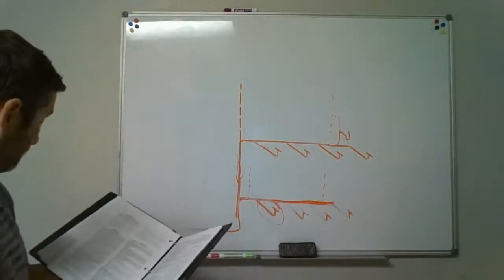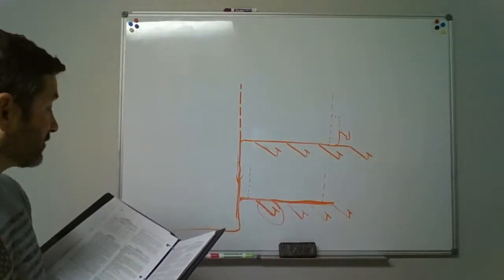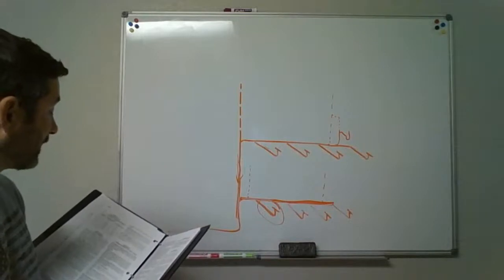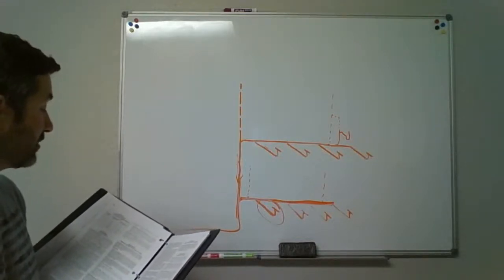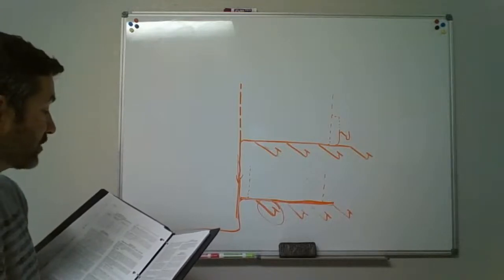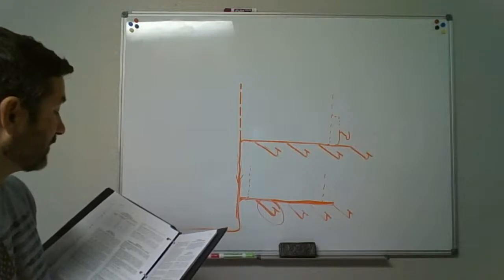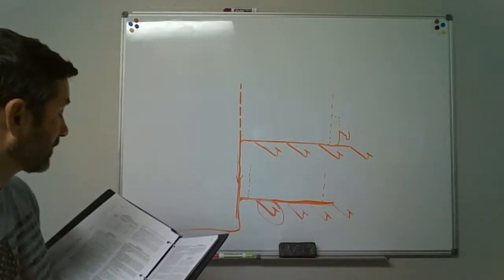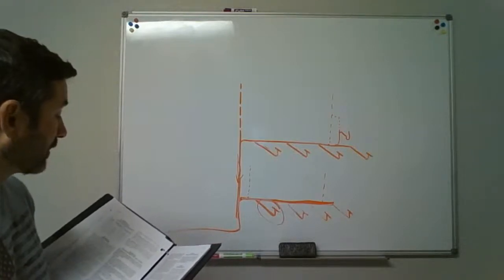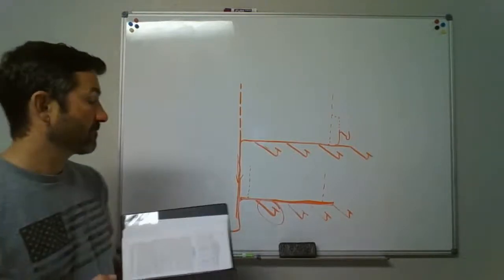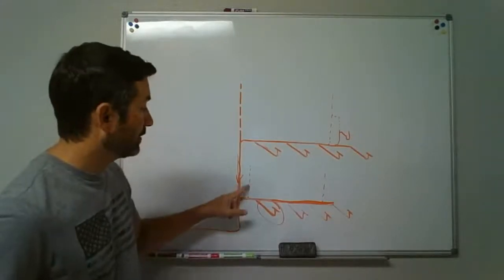The relief vent shall be installed according with section 905. The relief vent is permitted to be a fixture drain or fixture branch for the fixture located within the same branch interval as the circuit vented horizontal branch. The maximum discharge to a relief vent shall be 4 fixture units. So we could say, relief vent.